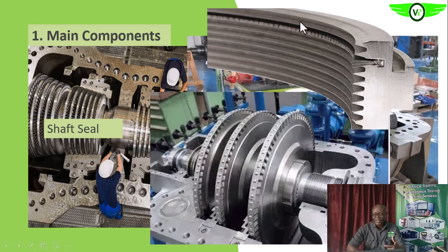As that is happening, as you are going along, the pressure will eventually drop to zero. Then at the outer end of the labyrinth, there won't be any steam coming out until such a time when the seal is already wearing out. Remember, it's a mechanical seal, and as this is turning, it can be eating the surface. Are we getting it? Of this labyrinth, because it will wear preferentially to the shaft itself.